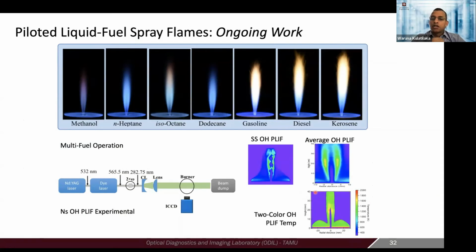When you burn kerosene or jet fuel, well, starting with a simpler fuel, of course, you get a significant amount of turbulence in this piloted liquid spray burner. So just to give a little background, we have a methane air pilot flame, and in this particular burner we have an injector, basically a nozzle, creating a spray of atomizing liquid directly into the flow stream. The pilot flame acts as a stabilizer to have a steady state spray flame.